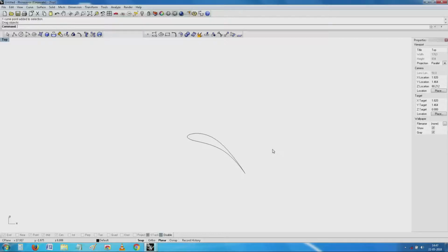This is how probably a cross section of the blade looks like. It looks like what is called a cambered aerofoil. Now comes the very important thing, why is it required? Why is this very peculiar shape given? When the air enters, typically it enters axially. When it leaves, because of this rotation, it has a tendency to also go at a slightly different angle.